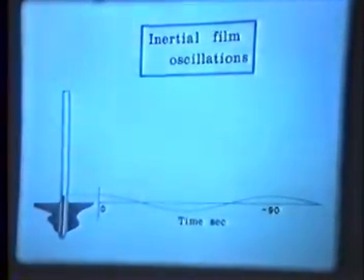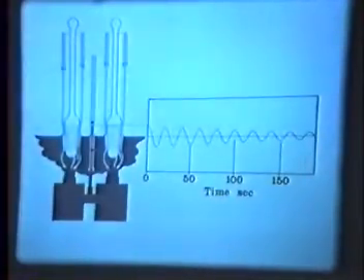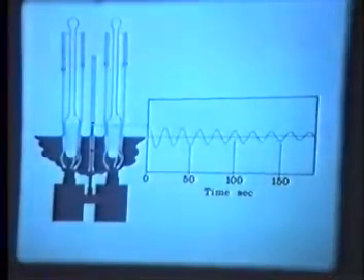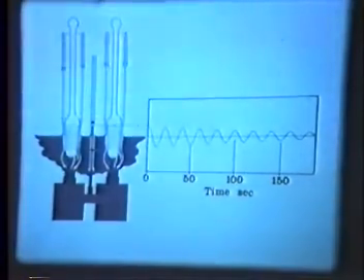We can keep the observation tube very narrow, say 1.5 millimeters in diameter, as the central standpipe here, and make the potential energy change, the amplitude, occur in it, while we increase the mass of the moving film by having two large side arms carry the film. We thus increase the inertial element by a factor of about 50, which increases the total swing to 5 or 6 millimeters and decreases the period to about 20 seconds.